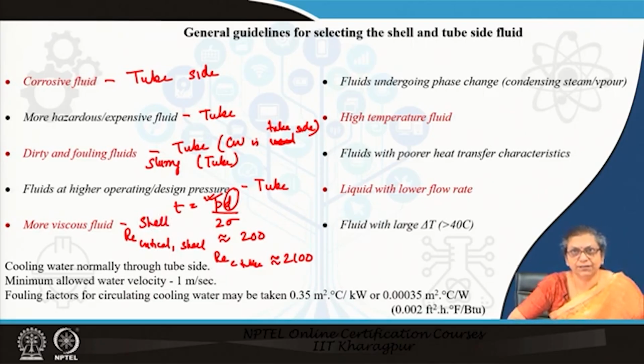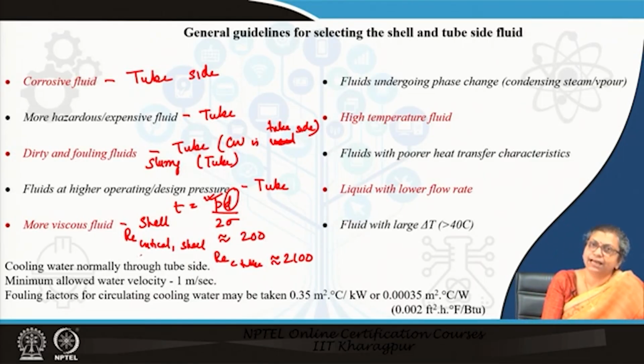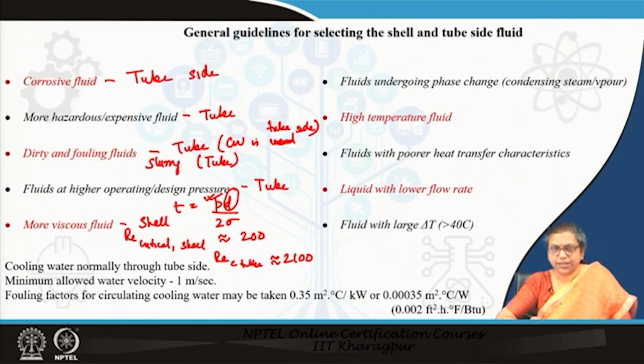But remember one thing, if the fluid is so viscous or the velocity is so less that even in the shell side it exhibits laminar flow characteristics, under that condition, in order to increase the velocity, we would like to introduce the fluid on the tube side.